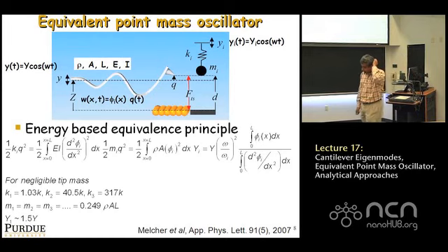We know how to do this now, but at the end of the day, we do want to retain the simplicity of the point mass model. Remember, the concept of the point mass model was that I replace the whole beam by a spring of the static spring constant and just allow the mass to be the tip mass. Now we realize everything's off. We had to throw all that out of the window because now you had to consider this as a continuous beam with its inertia, everything. So how do we get back to the simplicity of the point mass model?